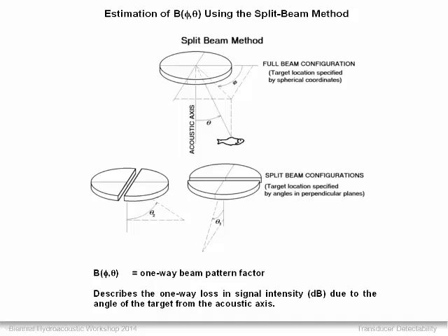That's just the whole method the split beam system uses to position fish, where it transmits on the single element, and then that element's divided into 4 quadrants on the receive side when those echoes come back. What that graphic's showing is from the phase, the arrival time, really the angle that returning sound front is encountering the transducer face. It can get a left-right and an up-down or bow-stern angle, and then position that fish in the beam.